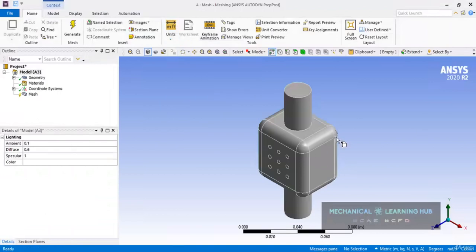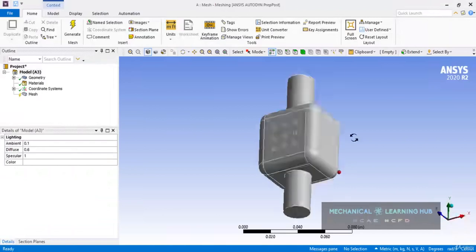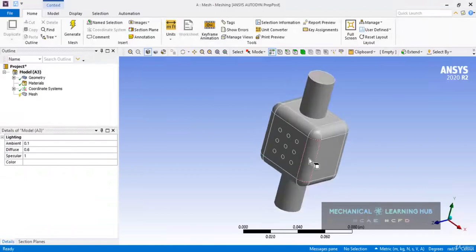Now this CAD file contains a single body representing a component in the ventilation system. Alright, almost all mesh methods can be applied here. The selection of which method to use depends on speed, memory usage and requirement of defeaturing and any mesh specific solver restrictions. We will demonstrate how different methods are applied and highlight important differences in the resulting meshes. Alright, so let's get started.